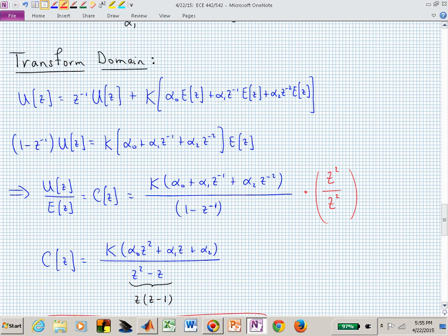That pole at Z equal 1, the integrator term in the PID controller, gives us this Z minus 1 factor. And what's that do? That helps us with steady state accuracy, just like it did in the analog. The more integrators you put at the origin, the better the steady state accuracy. But what are you doing to your system? You're maybe making it more difficult to stabilize and respond in the transient. It's this trade-off: transient behavior versus steady state accuracy. Those two usually have to be weighed against each other.